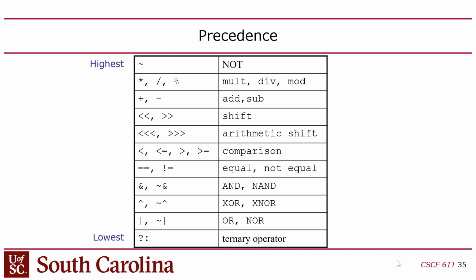less than, equal, and then there's also equal and not equal. Now, this is not an exhaustive list, by the way, but there is a variant of the equal operator. There's double equals, and there's triple equals, right? There's three equals. And likewise, there's not equal and double not equal. The difference has to do with the four-state logic. Remember that in Verilog, there's four states, but in reality, there's only two states, 1 and 0, right?